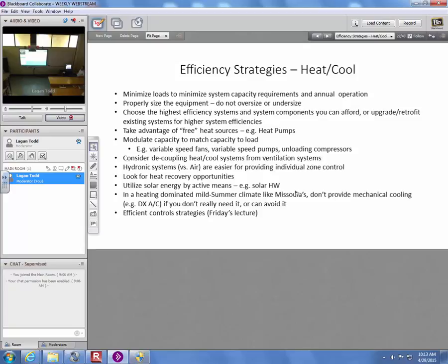But the reason I bring this up is because I see a lot of scenarios where somebody says, well, my priority is energy. I want the minimum energy footprint, and I understand these heat pumps are the most efficient. The heat pumps can be the most efficient way to heat and to cool. But now you put a heat pump in, and because it can provide heating and cooling, and you didn't have cooling before, you've actually just added a new feature that costs something. So the heat pump is even more efficient if you only use it for heating and don't run it at all in the summer. But most people aren't going to do that.